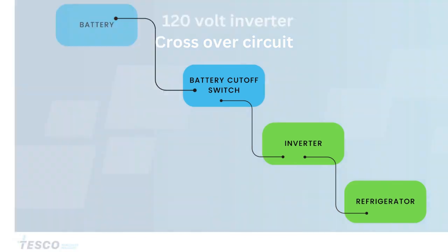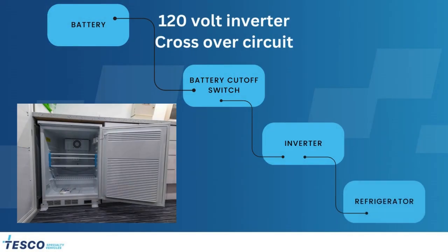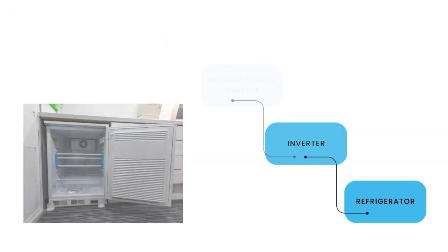Keep in mind, though, that the inverter is using battery power. Lots of battery power. Without the battery being charged by the converter or the engine, it may go dead quickly. Keep a close eye on battery levels using the battery gauge on the inverter control panel.